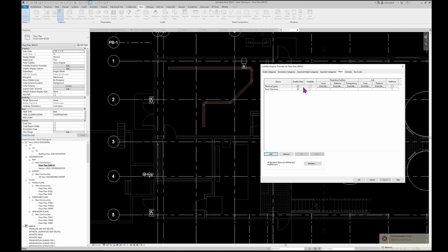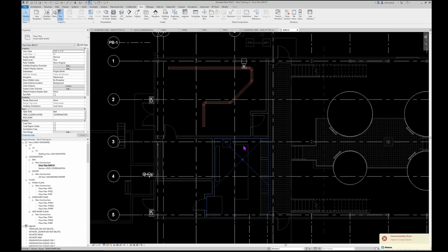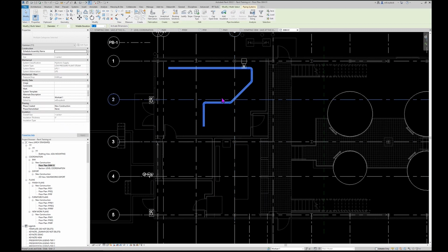The other side of it is that you could also make what's called a selection filter. In this case, I'm going to tab through and select everything here. This is a selection. Once you make this happen, you can save it. You'll notice here when I had these selected, after more than one element, this is the selection set.